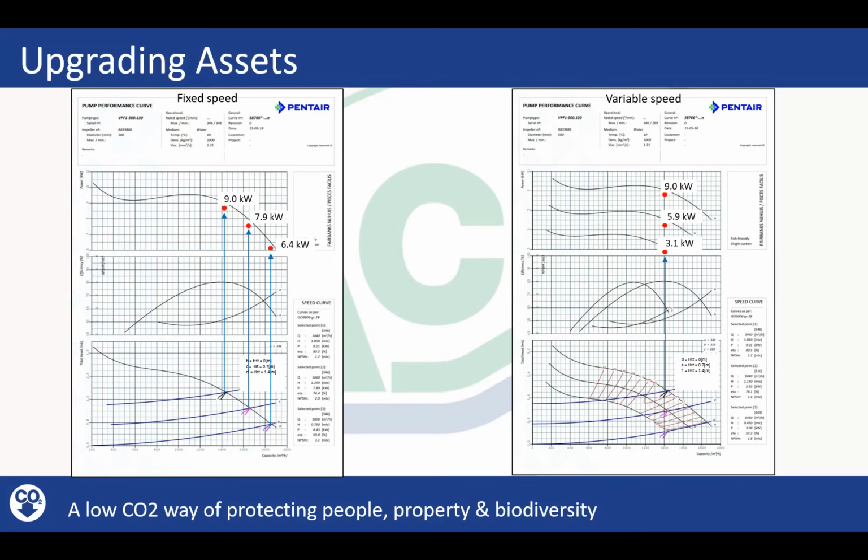So it can operate anywhere in between here, but the pump is going to constantly try and operate at that exact same flow all the way through the different heads. Now you can see that there's a direct reduction of between 25 and 52%. So you can see the kilowatts drops off further when the pump slows down than it does when it speeds up. But of course you might say, well, yeah, but I'm pumping more water. So what if the kilowatts are double?